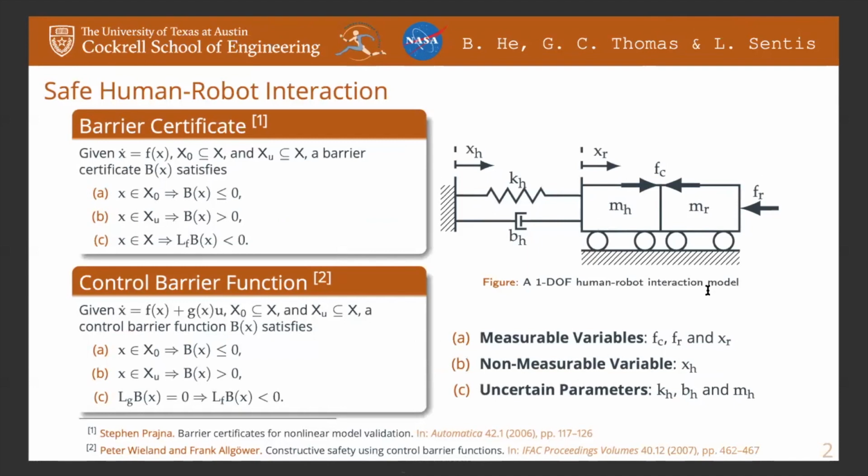Usually, safety verification is done by calculating the value of a barrier certificate. This barrier certificate is greater than 0 in the unsafe state space region and less than 0 in a safe state space region. Similar to a Lyapunov function, the barrier certificate decreases in the state space over time. If you can find a barrier certificate for a system, then the system is verified to be safe.